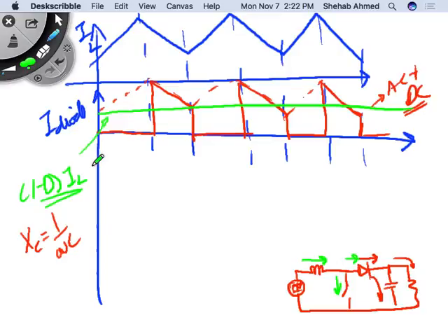That's why in discontinuous mode things are very different, because in discontinuous mode, the current comes down to 0 for a large portion of the period. So these are assumptions you cannot utilize there, right? But for the continuous current case, with small ripple, it's okay. These back of the envelope type calculations are what you need to design your circuit, right? This is the average value of current.